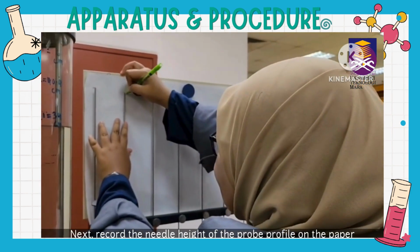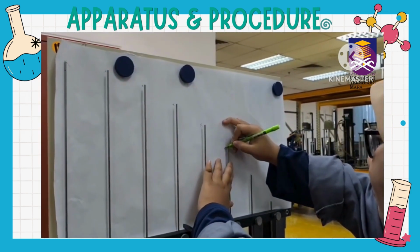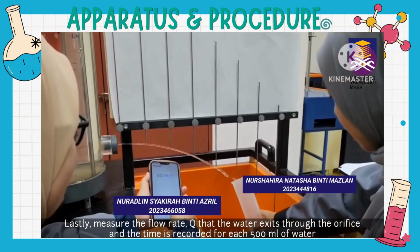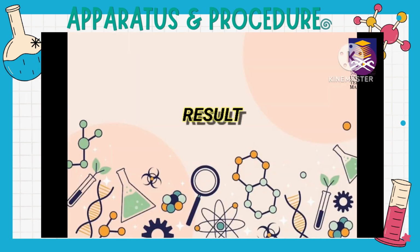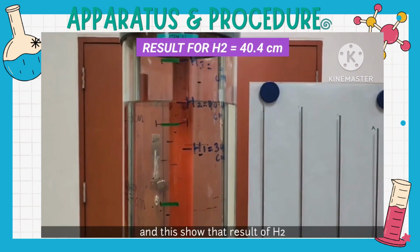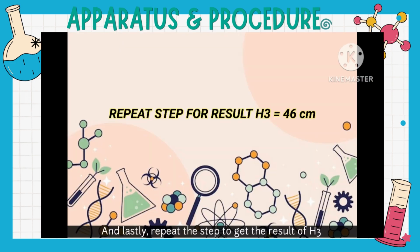Next, record the needle height of the probe profile on the paper. Lastly, measure the flow rate Q at which the water exits through the orifice, and the time is recorded for each 500 ml of water. This is the experiment result for H1, and this shows the result for H2. Lastly, repeat the steps to get the result for H3.